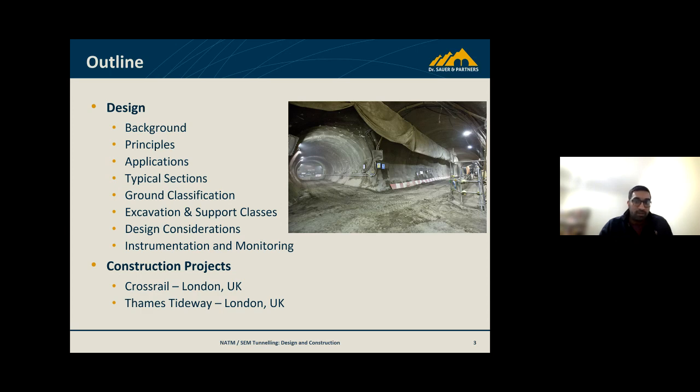Then the ground classification systems and support classes, so deciding on how you excavate and support the ground using those classification systems. Then design considerations, and instrumentation and monitoring to check that what we're doing is correct and within the specifications, and that things aren't going to fall down, mainly.